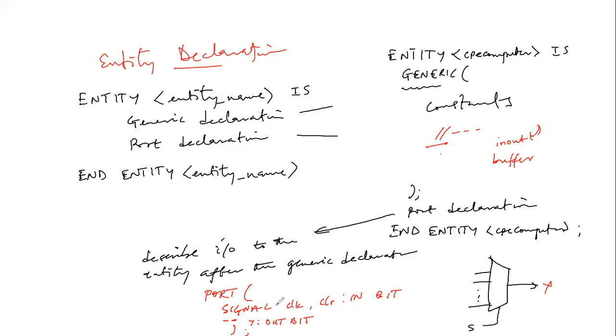And then in that architecture, just the way we have all of these keywords here, in terms of declaring the architecture, we say architecture, then put up the identifier, architecture of this entity name, okay? And then you now tell what exactly you want. We are designing a MUX, okay? So we now begin to link up all of these interfaces, how the input and output relate, okay?